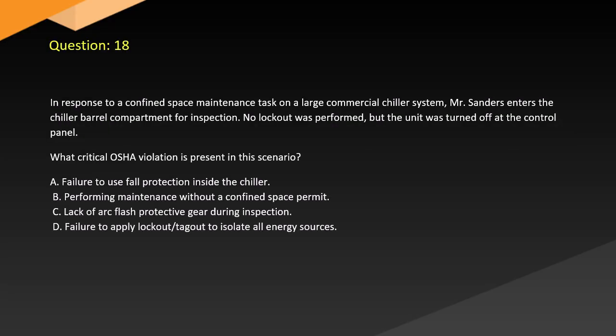Question 18. In response to a confined space maintenance task on a large commercial chiller system, Sanders enters the chiller barrel compartment for inspection. No lockout was performed, but the unit was turned off at the control panel. What critical OSHA violation is present in this scenario?